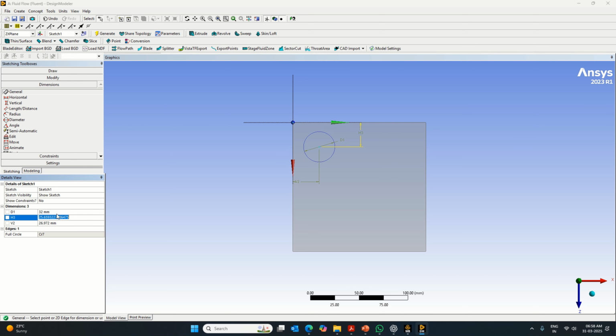The thing is, the total dimensions are 136 here, and this is also 136, out of which the fins are of length 126. So I will give 5 distance in addition to this. 16 will be the radius here, as 32 is the diameter. So 16. Then 126 is the fins dimension which is present here. Accordingly we are going to specify the distance.